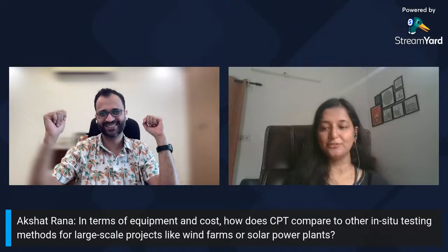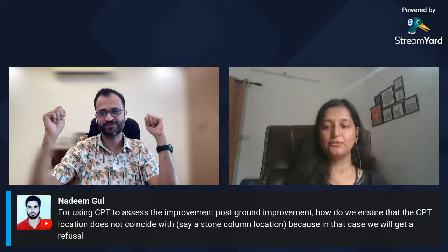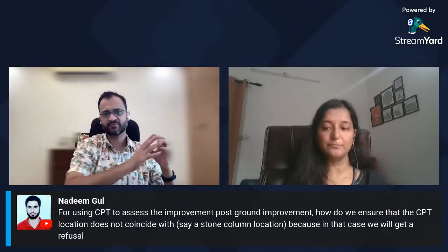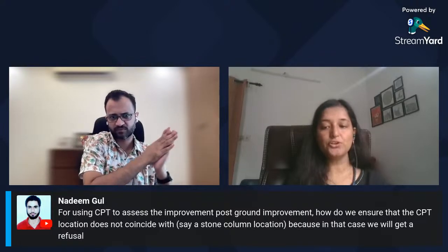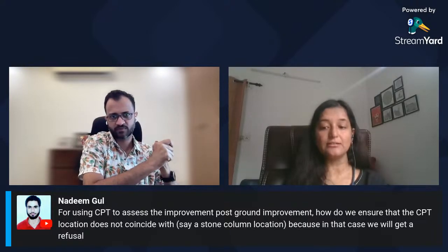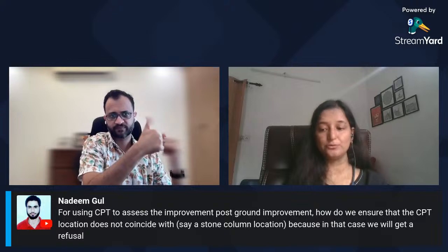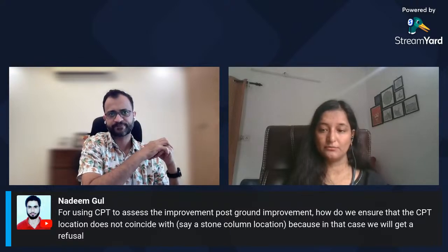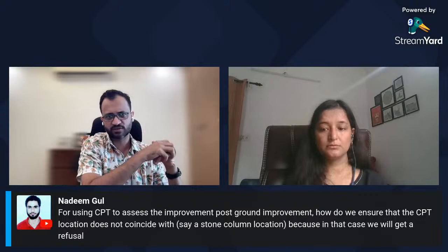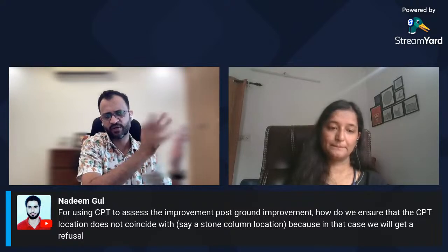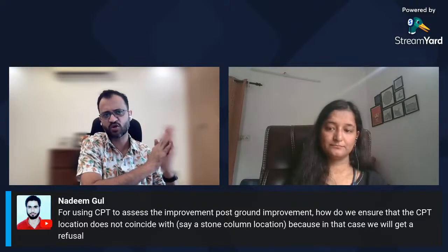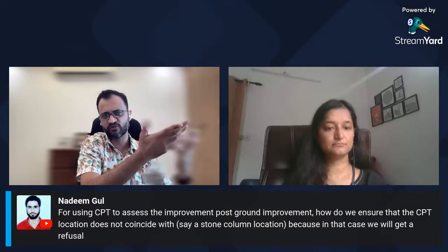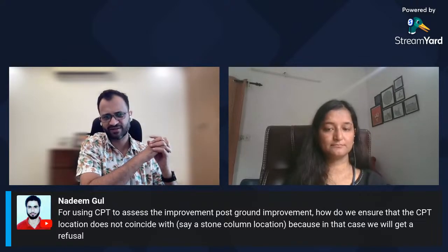And we are taking the last question of today. It is from Nadeem. For using CPT to assess the improvement post ground improvement, how do we ensure that the CPT location does not coincide with, say, a stone column location? Because in that case, we will get a refusal. Yeah, Nadeem, great question. So obviously, if you're doing CPTs in between stone columns, there's always an off chance that you might encounter a refusal because of the gravel.